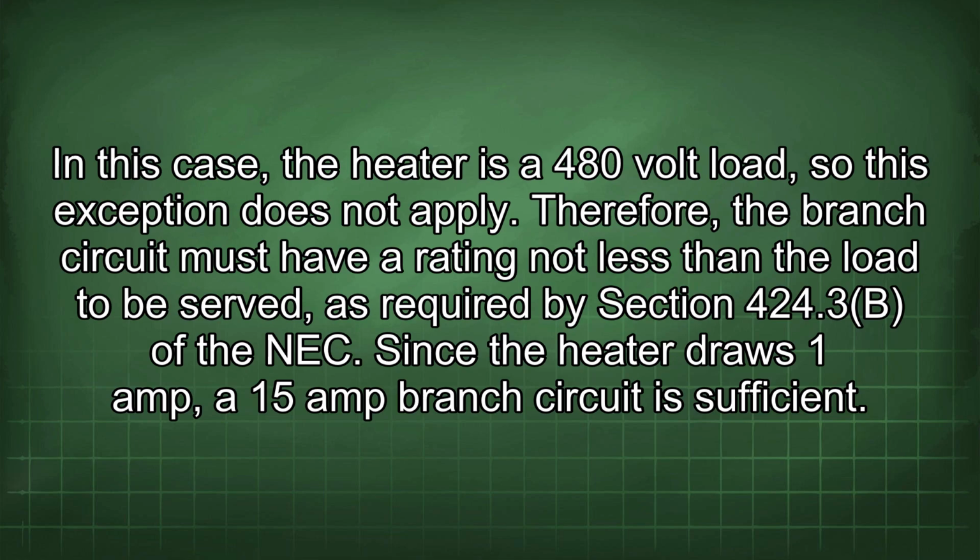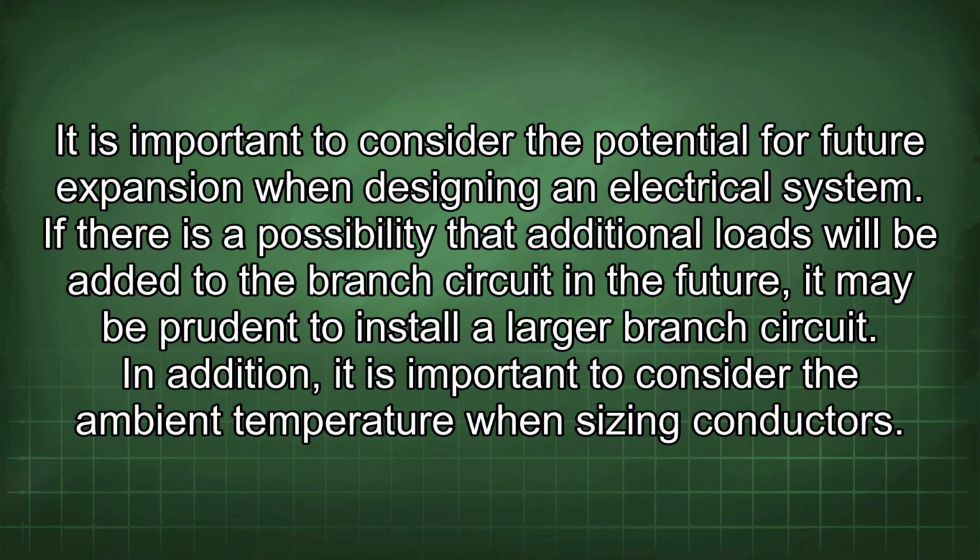Therefore, the branch circuit must have a rating not less than the load to be served, as required by section 424.3(B) of the NEC. Since the heater draws 1 amp, a 15 amp branch circuit is sufficient. It is important to consider the potential for future expansion when designing an electrical system. If there is a possibility that additional loads will be added to the branch circuit in the future, it may be prudent to install a larger branch circuit.